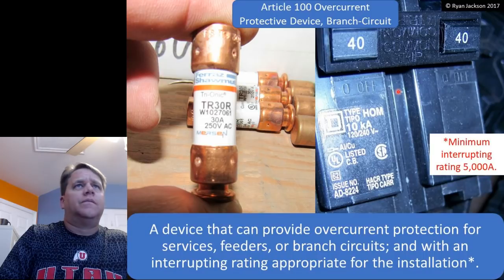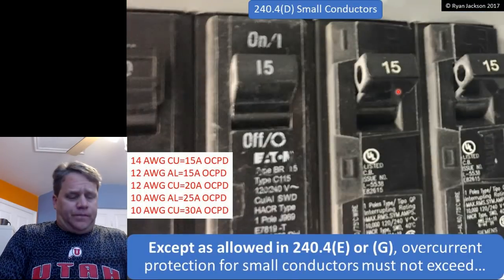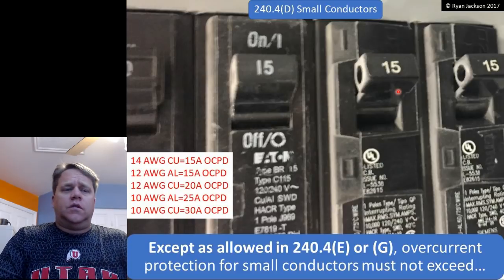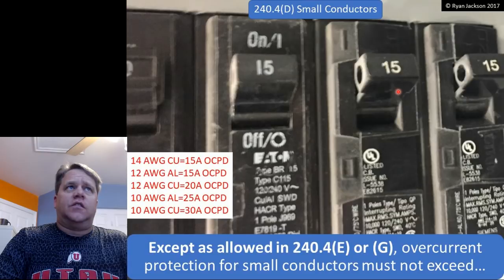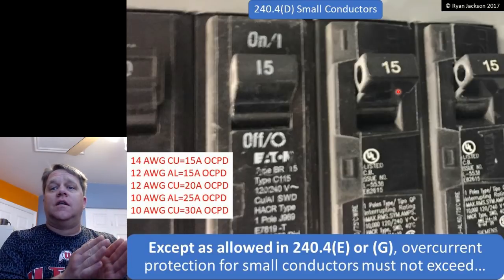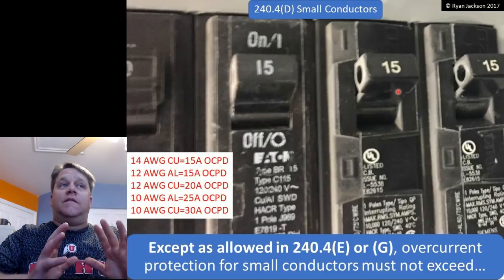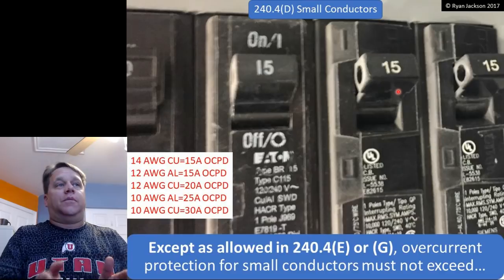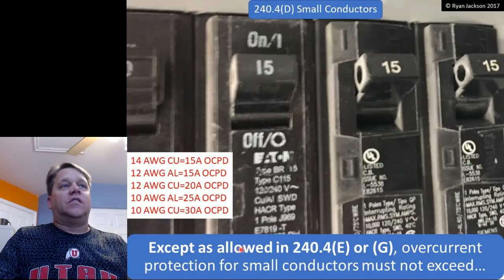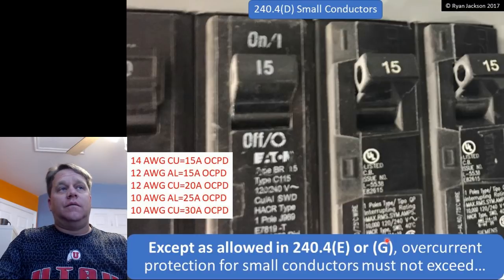Let's get into the rules. Starting with the conductors, we get into Article 240, and 240.4 is the general rule that talks about how we protect conductors. And I want to start with 240.4(D), even though it doesn't apply. And I want to cover it to be very clear that it does not apply. Take a look at the first couple of words: except as allowed in 240.4(E) or (G).